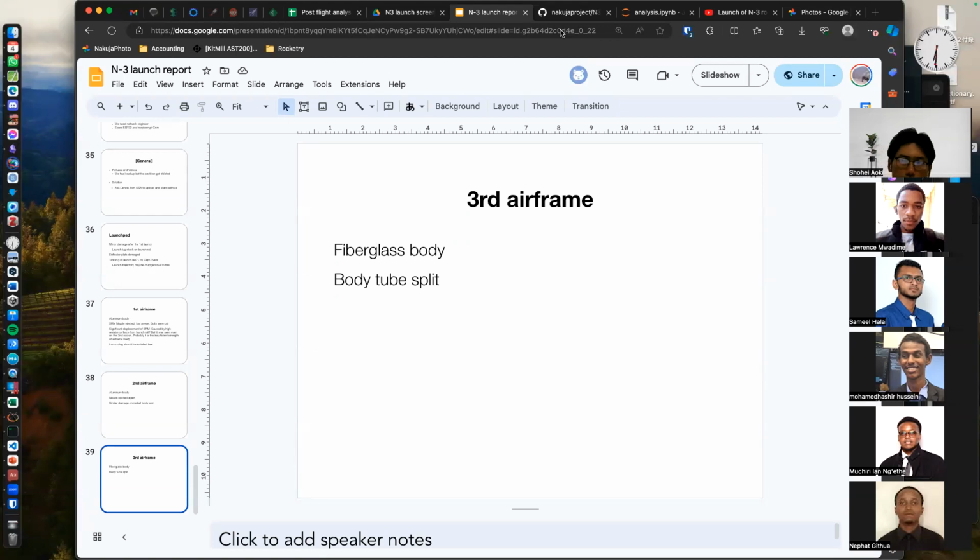Apart from that, the only concerns we had were the shears on the screws of the airframe, which meant that we now have to either rethink the connection of the SRM to the airframe, or consider strengthening the airframe, on which there are 2 options. We can use a stronger material for the airframe, or we can have an exoskeleton, and have the covering of the airframe just for aesthetics, while the main strength is provided by the exoskeleton inside.